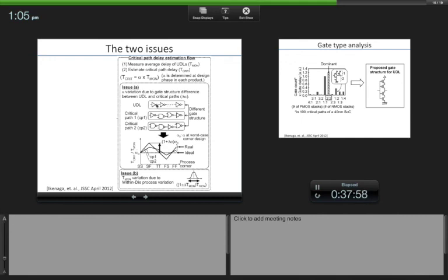So this is the monitor, that is a certain delay, right? And then the critical path has a certain delay. This is one critical path, this is another critical path. The paths are different, they have different gate structures, different amount of wiring and so on. You take the ratio of those 2. Now, if the ratio is exactly the same, some ratio, it doesn't have to be 1, it's some factor alpha, then you can program that alpha in there and you are done, because then you say my monitor gives me some number, I'm going to put in this factor alpha, and that alpha I somehow figure out, and then alpha times that value of the monitor is the delay of the critical path, right?